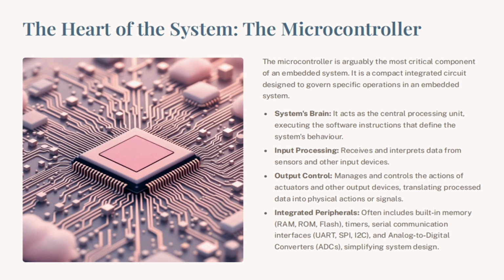translating processed data into physical actions like moving a motor or sending electrical signals. Integrated peripherals. To simplify system design, it often comes with built-in components like memory, RAM, ROM and flash, timers, and communication interfaces such as UART, SPI and I2C. It also includes an analog to digital converter